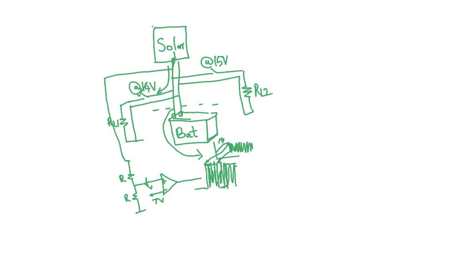So in order to avoid this, usually you're looking for a configuration where it turns on when you reach 14 volts, but it turns off at a slightly different voltage lower than 14 volts. So let's say 13.5 volts or 13 volts, let's say even 13 volts. So I want the switch to turn on when it's 14 volts, but I don't want it to turn off immediately after it goes below 14 volts. I want it to turn off only when it reaches a much lower value.